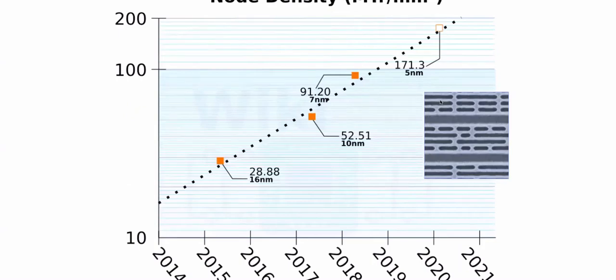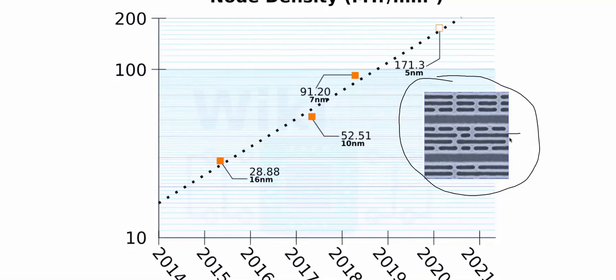I would like you please to look at this. This is technology. We have the transistors inside, but look how beautiful the lines are defined, how sharp are the corners, and this is talking about less than 5 nanometer technology. So how do you do 5 nanometer technology when you use optical lithography? The trick is to use enhanced or extreme UV technology.